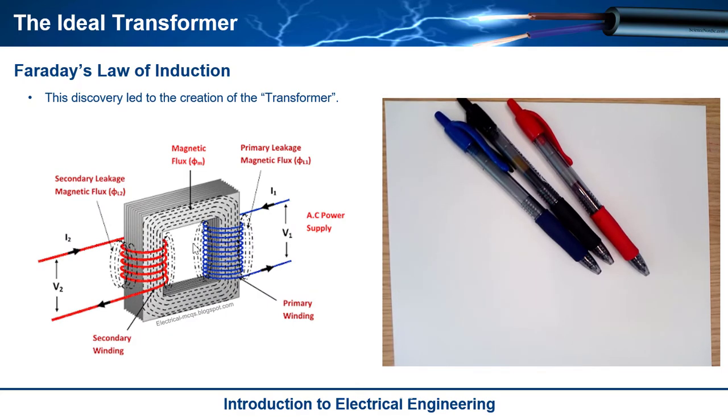This is an amazing thing where you have coils of wires that are magnetically coupled. The magnetic field lines couple between these two coils of wires. This was the big discovery that Michael Faraday made: if you run an AC signal through a coil of wires, it will create a magnetic field that, if you are close to another coil of wires, will couple onto that coil and cause current to flow. So you drive current into one coil, magnetic flux is created that is then coupled onto a secondary coil, and that coupling causes current to flow in the secondary. And these are not touching.